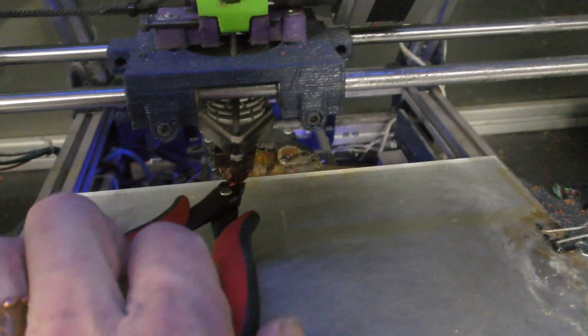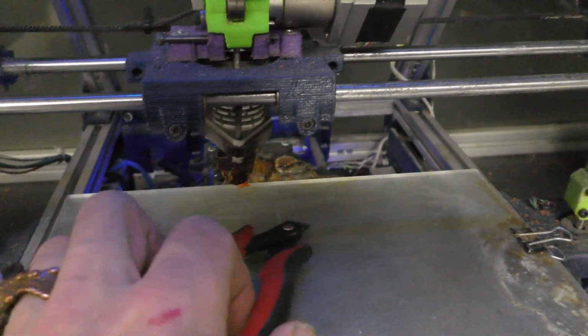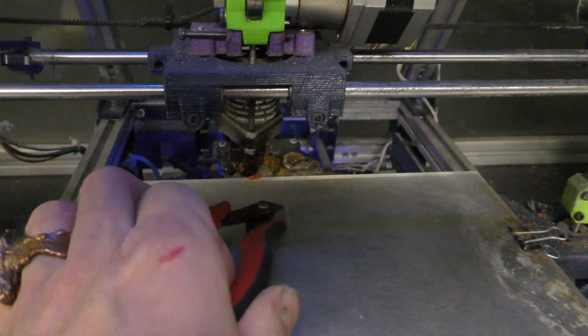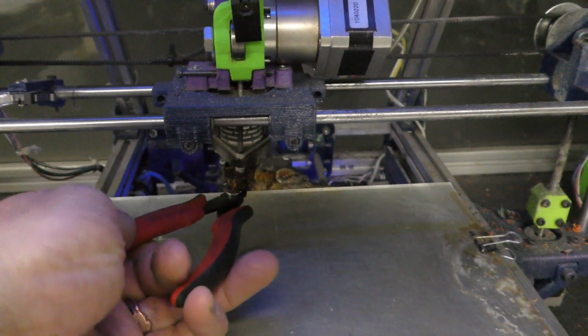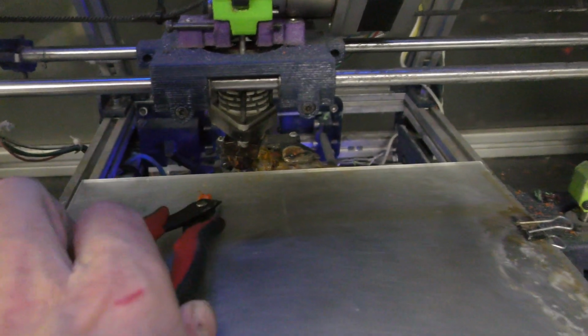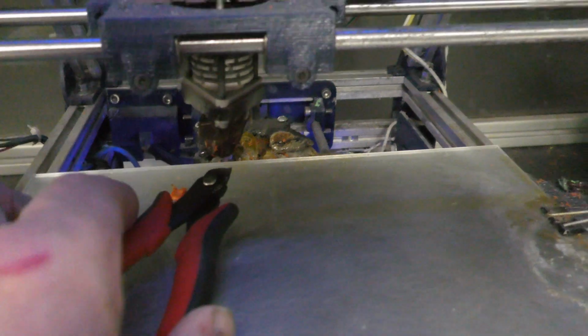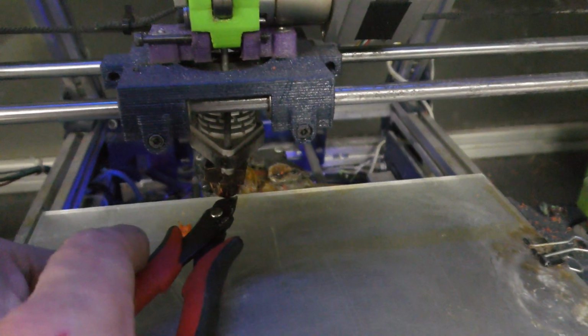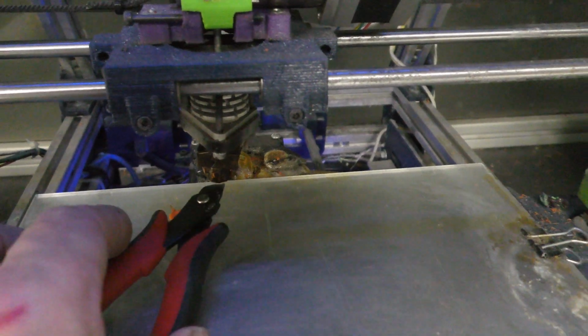So the first thing you need to do is kind of remove the goober that's at the end of the tip. Remove the goober, and do this with cutters. And do not mar the tip. In other words, there's a little tiny hole here at the end of the tip, and you do not want to ever use sandpaper on it or ever scratch it. So you want to do that very gently.